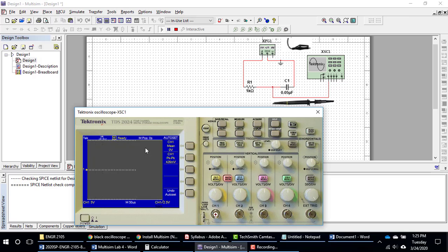What I'm going to do now is do a single. If I press this button, this will start and stop the oscilloscope. This button here will give me 1 screen's worth of data. So if I do that, I can adjust my vertical scale, and I can adjust my vertical position. I can adjust my horizontal position. Okay. So now you're in position to do some measurements.